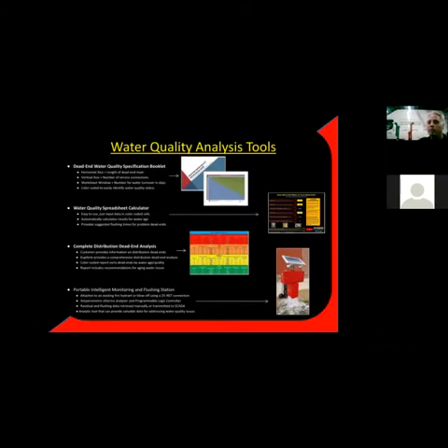And in the red box at the bottom of the page there, it'll actually tell you how many minutes per day, if you have aging water issues on that dead end, you should flush the line using something like an automatic flusher that does 200 gallons a minute. If you're going to flush it with a fire hydrant doing 1,200 or 1,500 gallons a minute, you can adjust your time. But it gives you an idea how long you need to flush to turn that line over 100%.